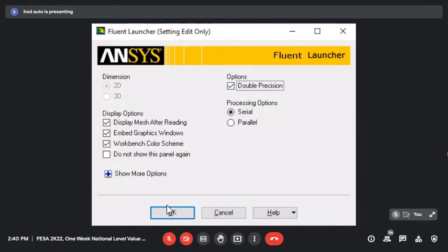Generally, I have situations wherein I am going for computational fluid dynamic analysis of gas turbine combustion, or a vehicle wherein I want to do exhaustive CFD analysis. I have to go with parallel processing rather than serial. Serial is for small jobs, where your iterative steps are around 10 to 15,000. You can go with serial, but whenever you have very complicated situations, you have to go with the things where they are split into multiple jobs.